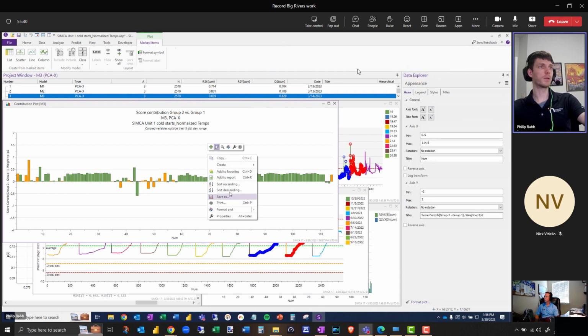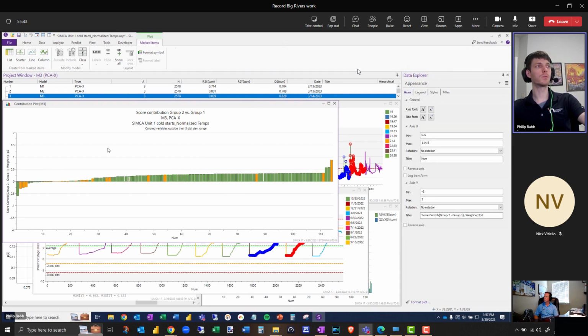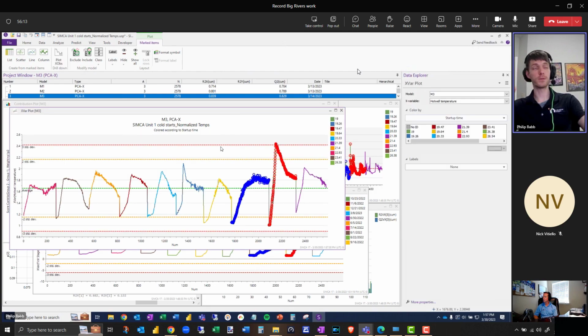And that's another really powerful thing about SIMCA: it's really easy to compare all of the contributing variables to the differentiation between how SIMCA sees each one of these in the model. In this particular example, it thinks that the hot well temperature, feed water temperature, and this duct temperature, the other air duct temperature over here, are the main drivers in the difference between these two data streams.